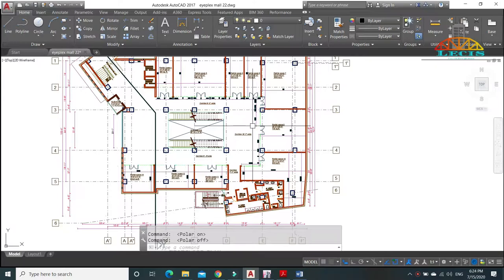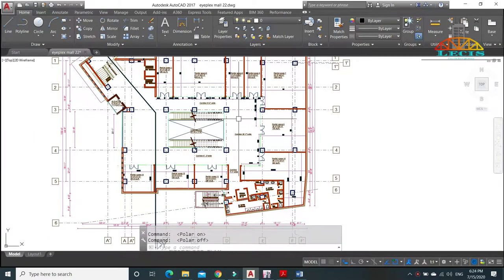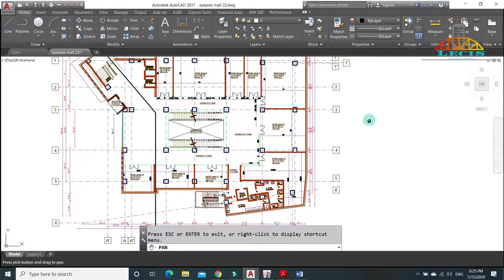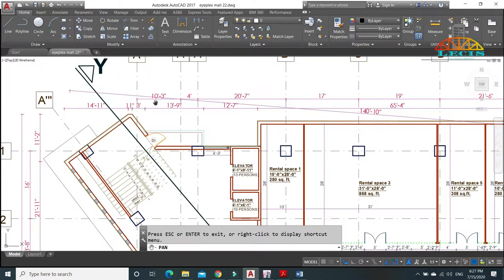We are not going to design every panel of slab, rather we are going to design the critical panel of slab. That panel of slab is critical, whose both dimensions are largest among all. So our first job is to identify the critical panel of slab from the plan. To find the critical panel of slab, you need to find the largest value of center to center distance of grid in both x directions and y directions. So at first I'm going for the x directions,